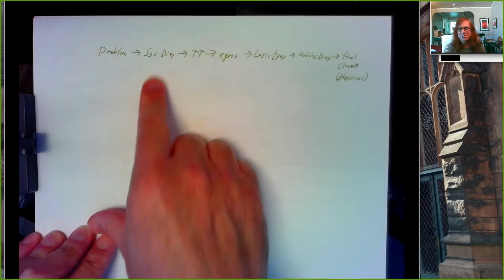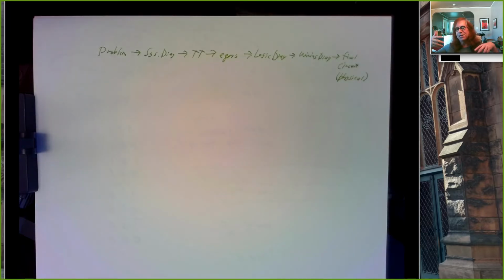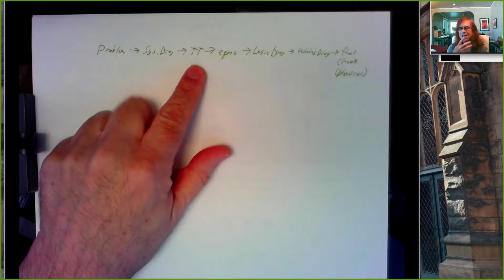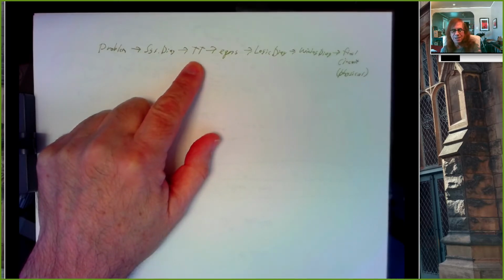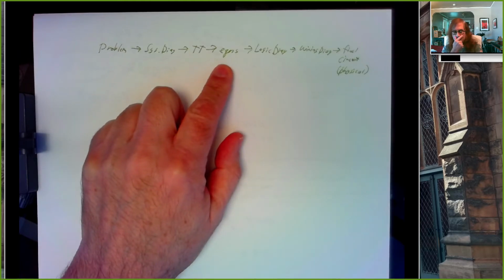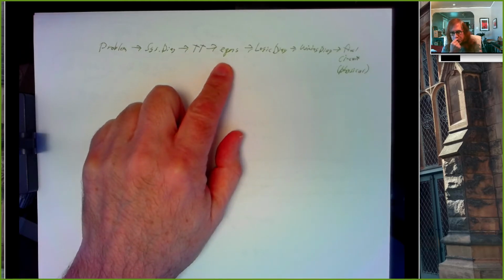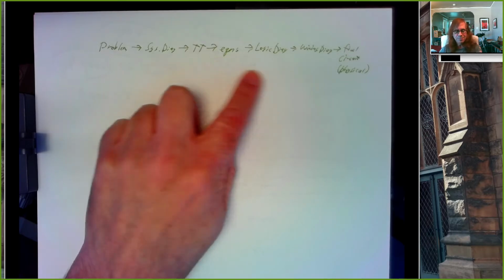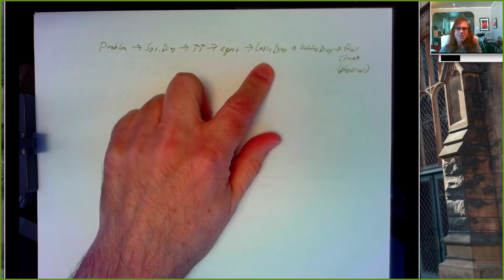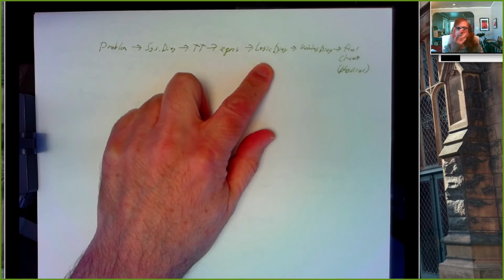The system diagram is the box that says what the inputs are, what the outputs are, and what the ones and zeros mean. The truth table describes how the outputs relate to the inputs. That's what you did in lab 1. Equations say what the Boolean expressions are, in terms of the inputs, that will generate the correct outputs. The logic diagram is the thing where we have the OR gates and the AND gates and wires connecting them.